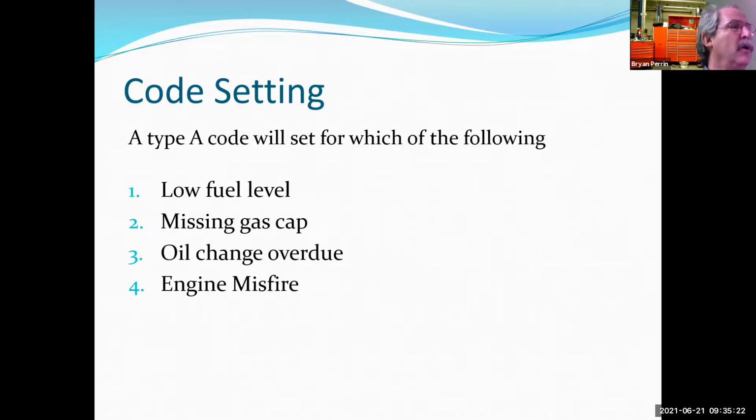And there are some cars that if you pick up a misfire when you're out of gas, it's still an A code, but it'll kick on and say you had a misfire while you were running out of gas. So at least it lets the technician know that you brought the car in with a check engine light, and yeah, you ran out of gas. And we look at the tank and go, oh, it's full now. Okay, let me go drive the car. If it runs fine, it's probably already fixed.